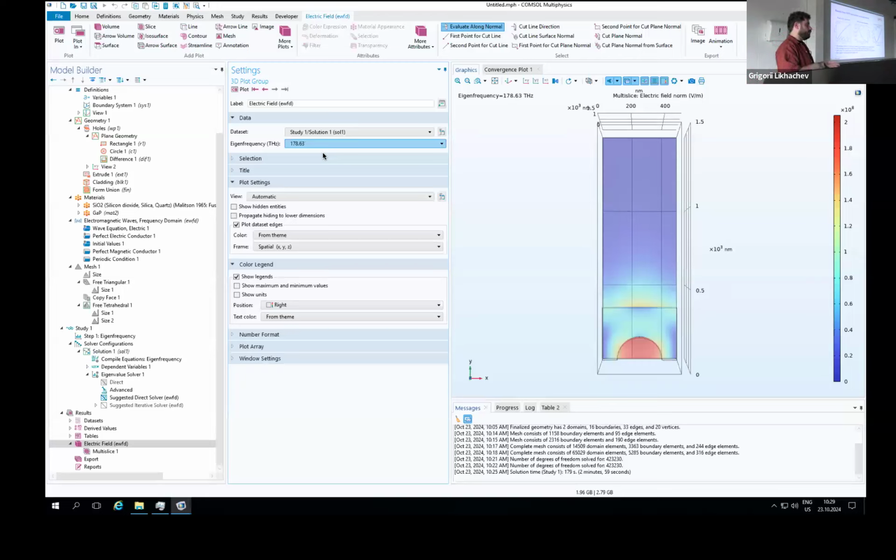And I hope that you bring with you that ring resonators are not perfect, they're very good, but if you want to, let's say, engineer the dispersion of a resonator point by point, frequency by frequency, here you can do it by engineering exactly where in your photonic crystal each frequency gets reflected. This is something that with ring resonators you can't control well. So either you get into these internal corrugations in the rings, or some waveguide width variation along the ring, something like this.